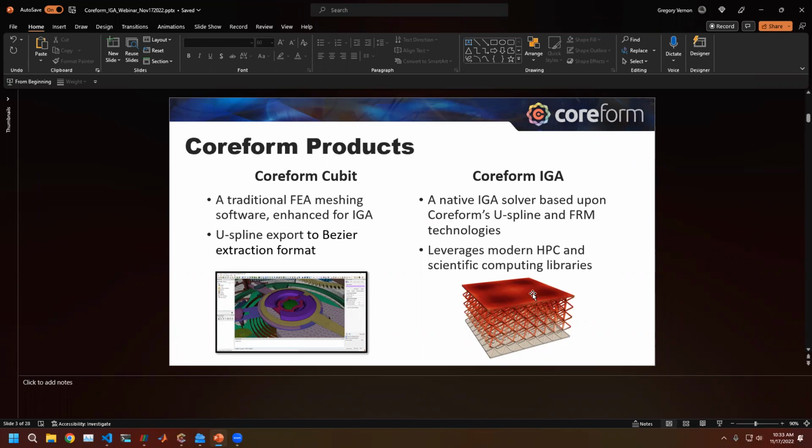All right. Here's another question. Can you give me an idea about the material library and the constitutive models available in IGA analysis? Can hyperelasticity and plasticity be included in the analysis? Yeah, so today we have a pure linear elastic material model, as well as a nonlinear elasticity, the neo-Hookean elasticity model. And we also have an isotropic plasticity model.